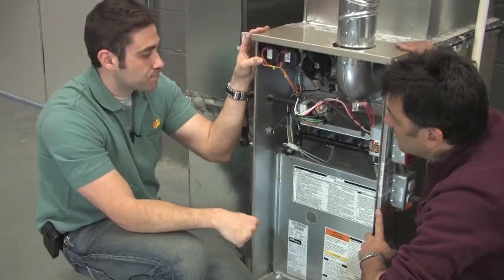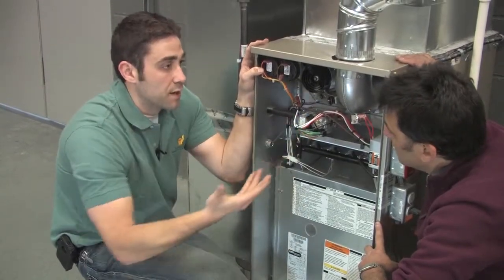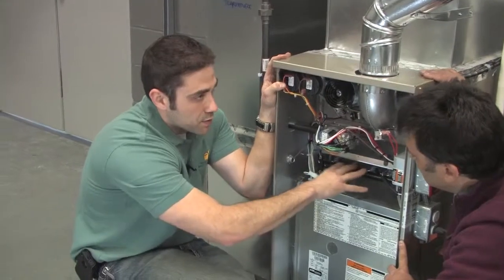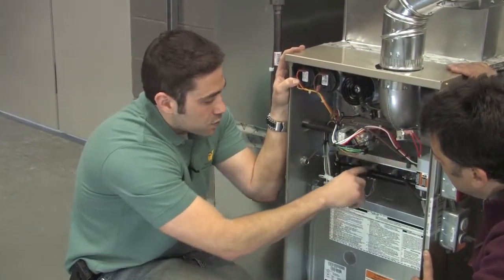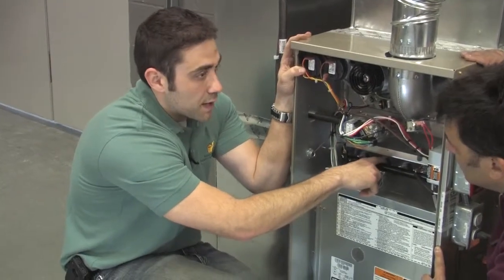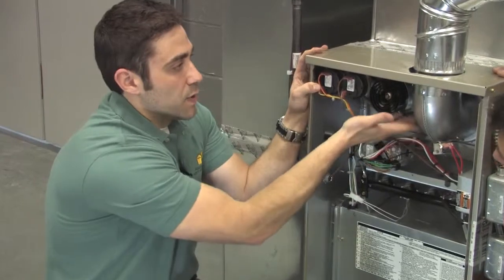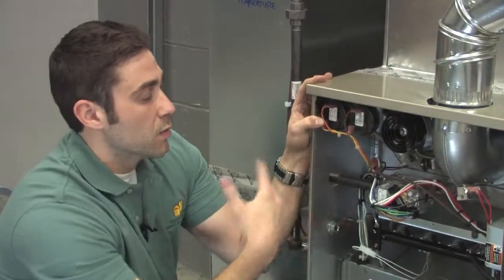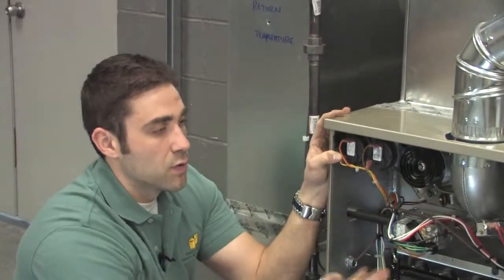something happened. So when we test this, there's no room for dilution air to come in. The only air that comes in through the process, the combustion process, is right here at the burners. So air is being drawn in because this fan is running. We have negative pressure here, and it's drawn in. It's able to mix with the gas that's coming out of these jets. As it goes through the heat exchanger, it burns, and it works its way out through the heat exchanger into our flue pipe. So in this system, we don't have to worry about where we're going to test. We're just going to test right on the flue pipe. We don't have to look for any dilution air.